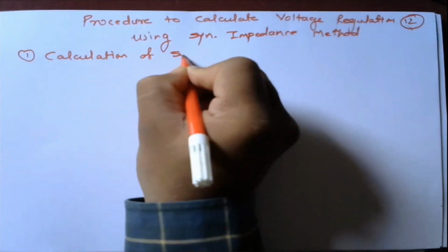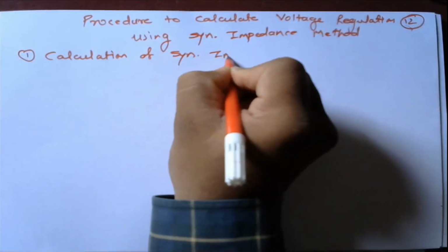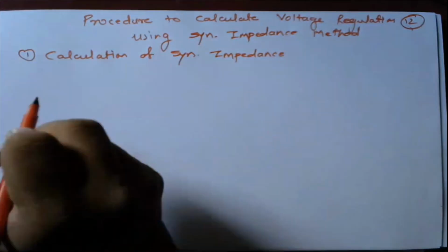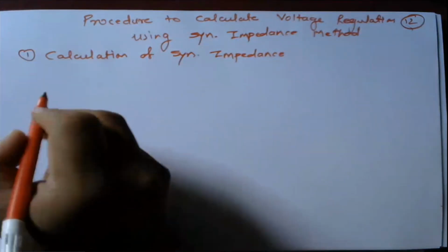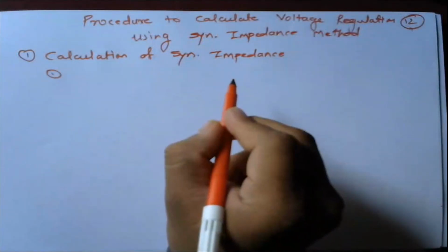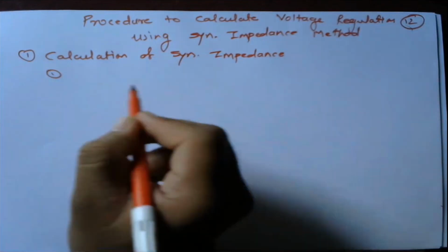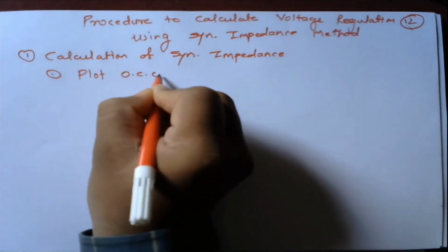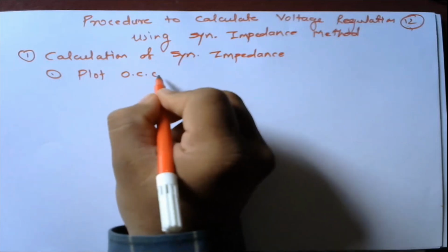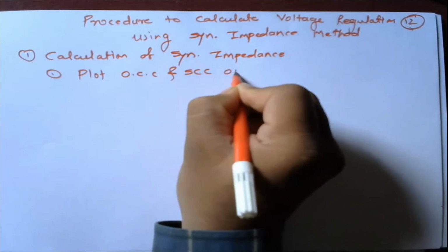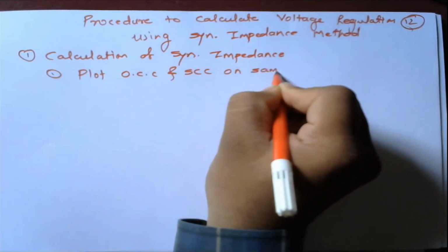Calculation of synchronous impedance. And to calculate the synchronous impedance, first we have to plot the open circuit test and short circuit test on the same graph. Okay, any doubt?